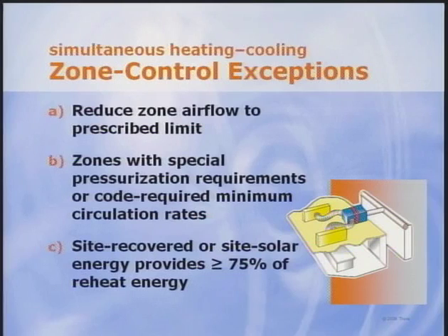You may do any amount of reheating if at least 75% of the reheat energy is site recovered or site solar. Again, this could be directly from refrigerant in the form of hot gas reheat or from the condenser water of a water-cooled system. Now, let's look at the zone airflow limits allowed.